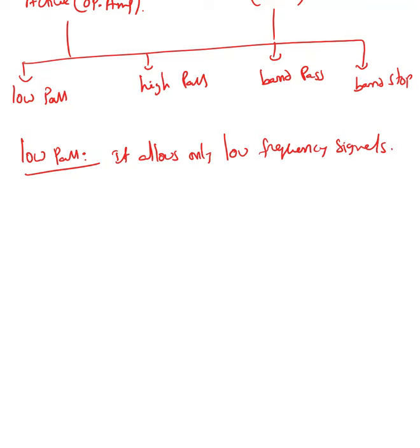Why do we need a filter, basically? For example, if you look into your radio circuit, the local radio station here is KMUW, which is 89.1 megahertz. So 89.1 is a little bit of a high frequency. The filter circuit is going to filter out all other frequencies and take the signal at that 89.1 megahertz frequency. So a filter is nothing but something that allows the wanted signal and rejects the unwanted signal. That's what a filter is.